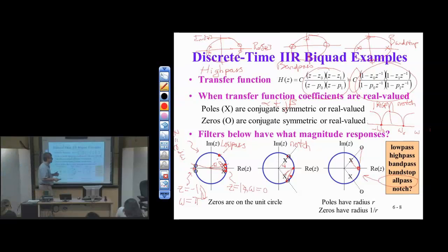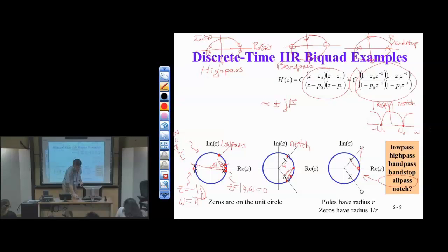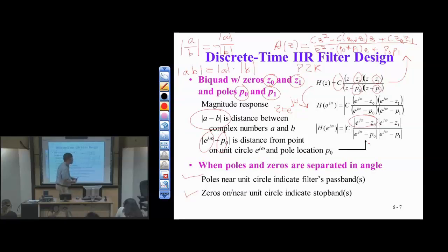Now what do I do next? I'm not yet at coefficients. I'm still in poles and zeros and gain. What do I do? It's not meant to be difficult. Multiply out. That's it. That's all you do. Now you have a filter. Now you have a biquad. So once you know Z0, Z1, P0, P1, you multiply out those values, as we saw in the previous slide, to simply get your coefficients.